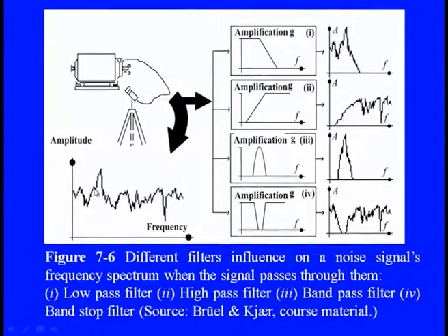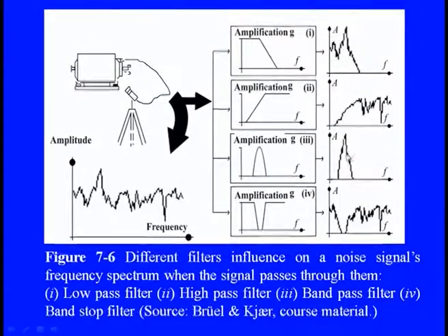If we want to analyze this, we need to allow the range within which it falls, at that frequency and with the corresponding amplitude. If you look at this amplified part, this is what is being allowed, and the remaining lower and higher frequency regions are straightaway stopped. So, in this raw signal, this is my vibration signature, which clearly shows that in this particular frequency region you have this kind of frequency spectra.